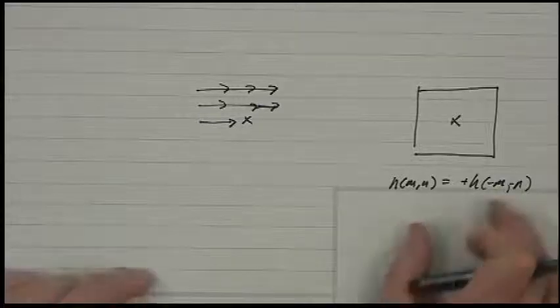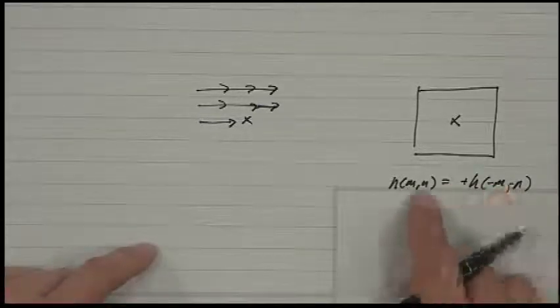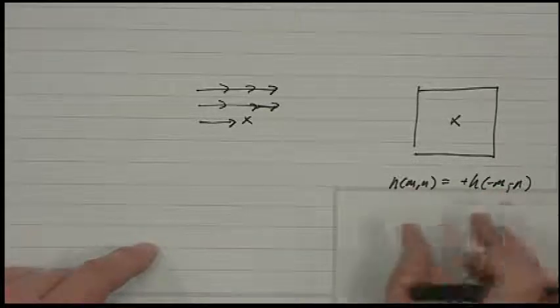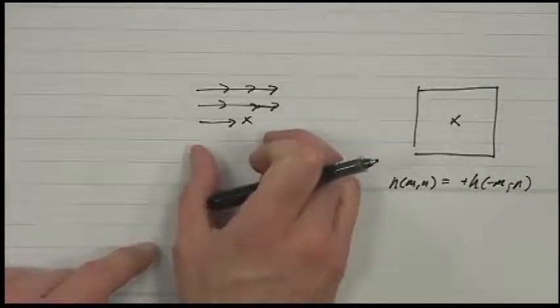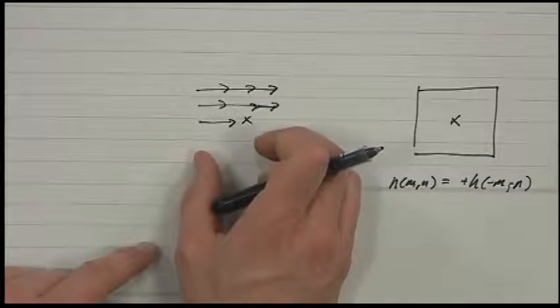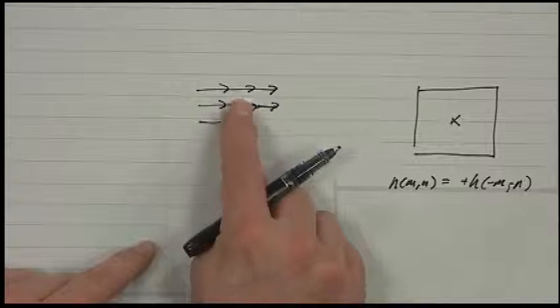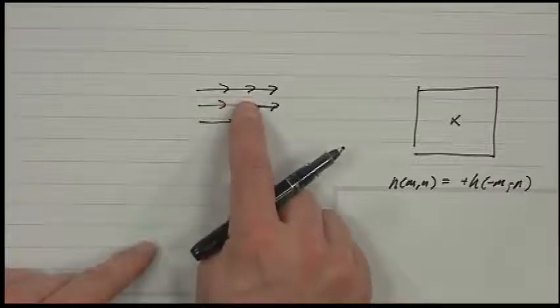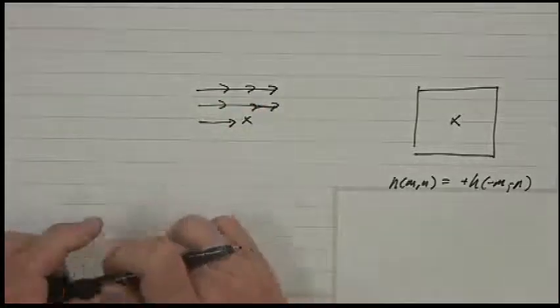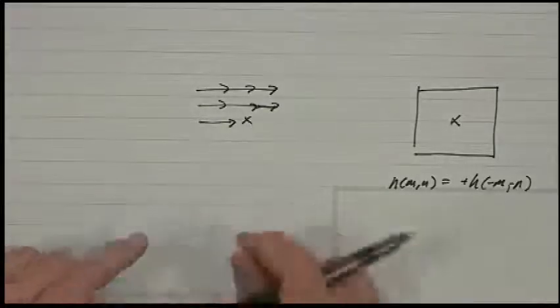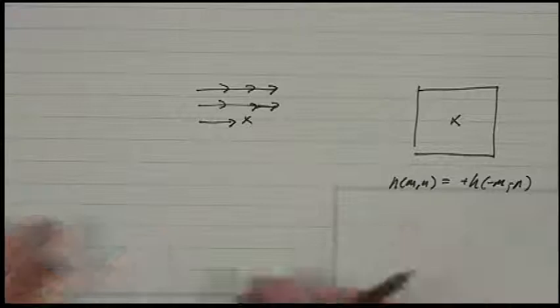So that's a linear phase filter, and if you delay that by a fixed amount of time, it's still linear phase. An IIR filter generally can't be designed to be perfectly linear phase because you can't get perfect symmetry in the impulse response. You can get close to linear phase, and that becomes a numerical optimization problem. But if you need perfect linear phase filters, then you usually use FIR.